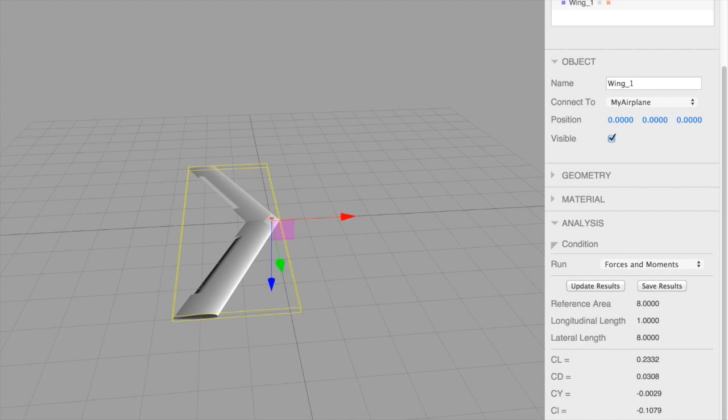Now if we had stayed with aerodynamic coordinate systems, then the direction of these are not always intuitive. But in this coordinate system, the flight mechanics coordinate system, these are very intuitive, and they all follow simply the right-hand rule. So our rolling moment is negative when the aircraft wants to roll to the left. And you'll see that with positive aileron deflection, this aircraft wants to roll to the left.